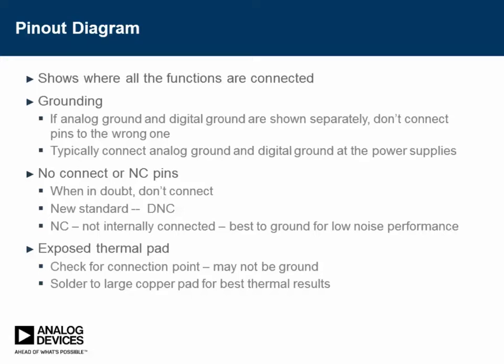We'll often have pins that are called NC, which means no connect. In some cases, an NC pin means we have a part which has 25 operating pins, and it's a 28-pin package. So there's three pins that are NC, not connected. We've also gone to a new standard called DNC, do not connect, and that means that it was a pin that we used for some sort of testing function, but you should not be using it because it could disturb the performance of the product.